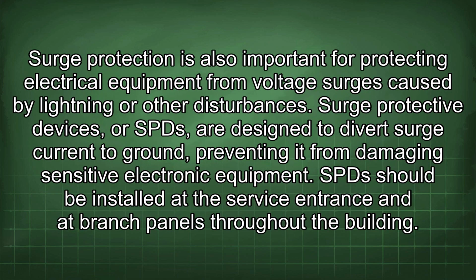Surge protection is also important for protecting electrical equipment from voltage surges caused by lightning or other disturbances. Surge protective devices, or SPDs, are designed to divert surge current to ground, preventing it from damaging sensitive electronic equipment. SPDs should be installed at the service entrance and at branch panels throughout the building.